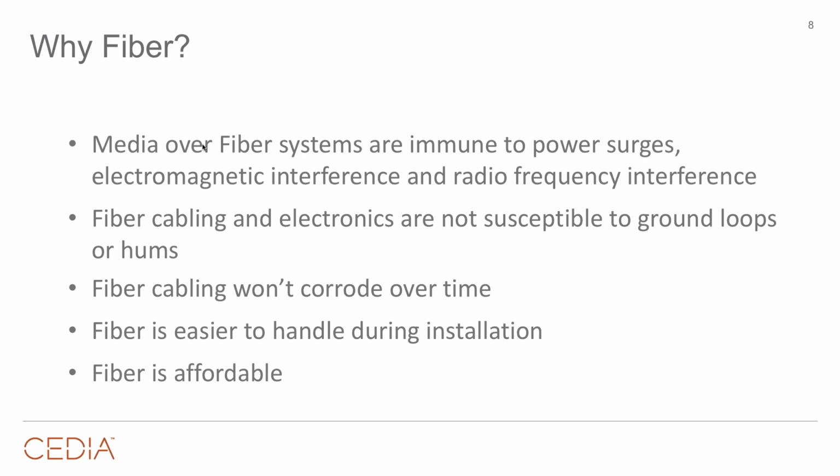If we think about that installation, right? What did we all learn in school when we started studying AV and starting to take our tech classes? We don't trunk cables. So one of the big issues of a twisted pair installation is that when we take our different cables, right, all of our different extenders and networking, and maybe throw a control cable in there or an amp cable in there, and we Velcro it together or we zip tie it together. Well, we're never supposed to do that, because what'll happen is you'll have crosstalk amongst those different cables, and crosstalk can knock out the individual signals.